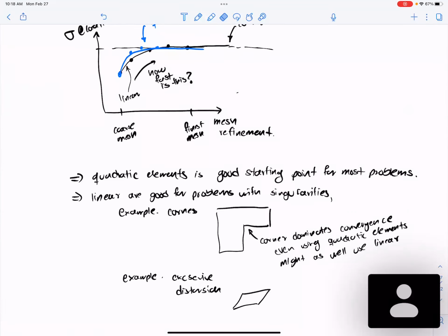But the problem is that's why you need to do this convergence analysis, because with that element, you will see in the next slide, the beam bending. You will see that with the cheapest element, linear with reduced integration, you can get just terrible solutions for particular problems. So we'll do the beam bending, and you'll see the beam will just bend excessively, and it's just not physical.